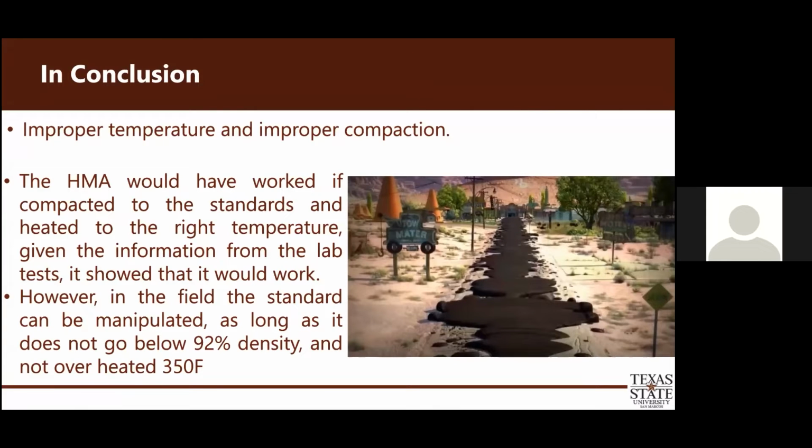So according to the data provided to us, we speculate that various factors affected the asphalt. Our primary reason is a lack of temperature control while setting the asphalt. If the asphalt is not set at the right temperature, the strength of the asphalt will be compromised. In addition to temperature, we found that compaction was also another leading factor.